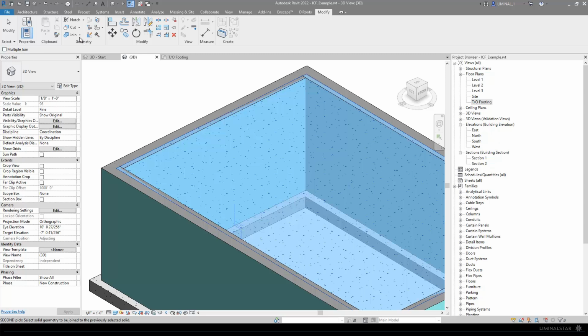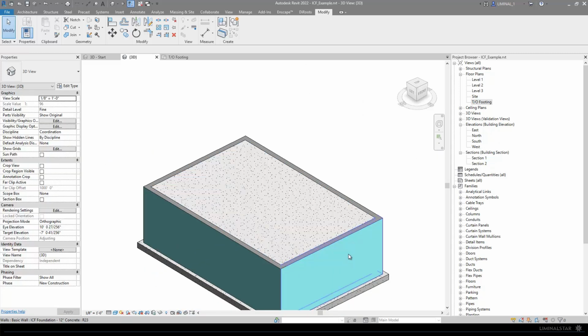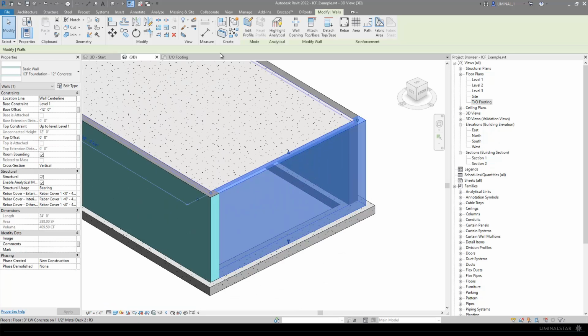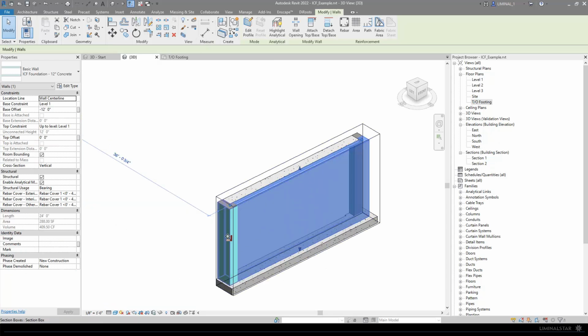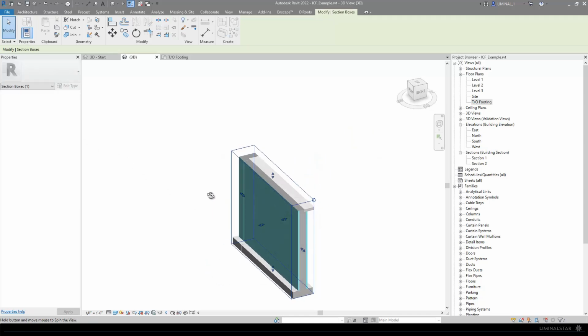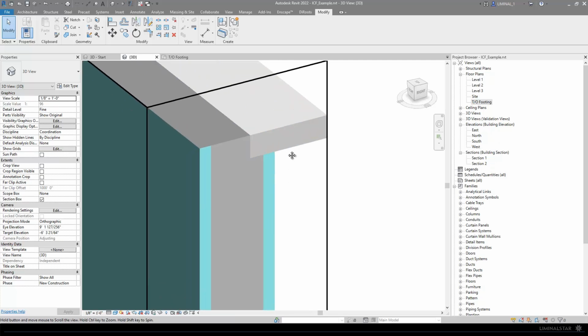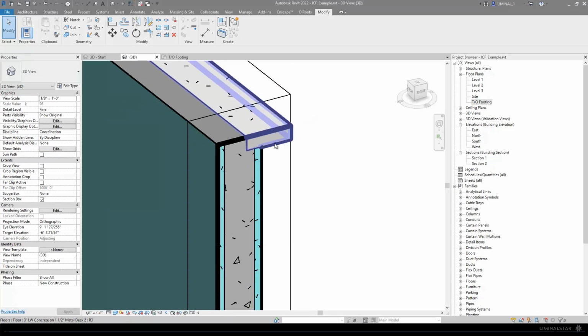So I didn't hit join multiple, I just hit join and then tab, and now that should let me click on the rest of them. And if we take any of these specific walls and we section them, you can see that the join command itself is actually doing that dirty work for us.